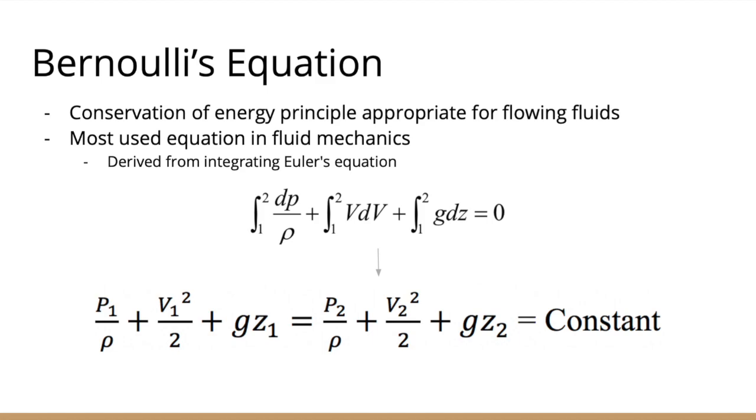To start off, one of the basic principles required for this project is the Bernoulli's equation. It is a conservation of energy principle appropriate for flowing fluids. Being one of the most used equations in fluid mechanics, it is derived from integrating Euler's equation between 2 points. Euler's equation states that for an inviscid fluid, the change in momentum of a fluid particle is caused by a body force and the net pressure force. Integrating it allows us to obtain values at specific points for the process.